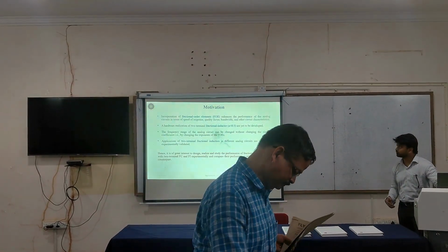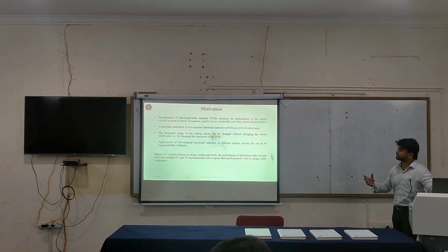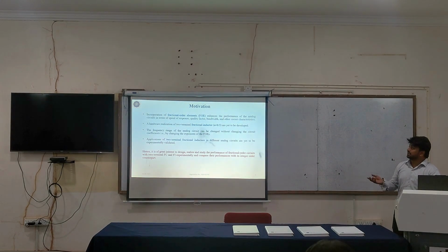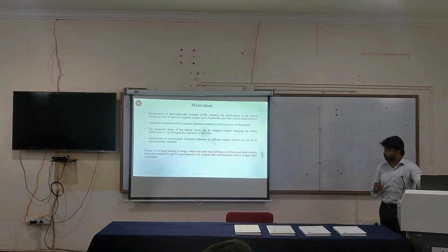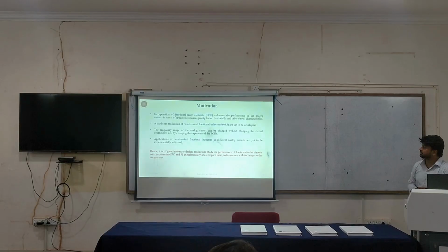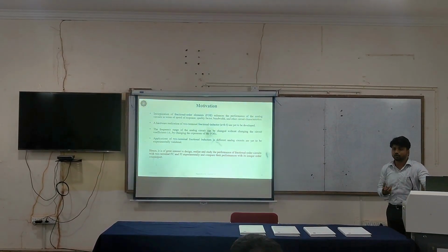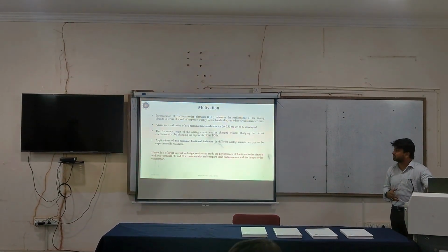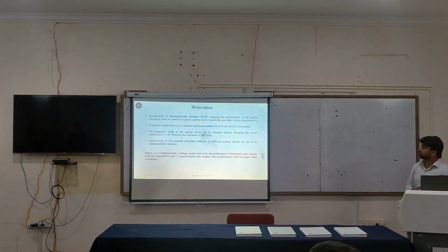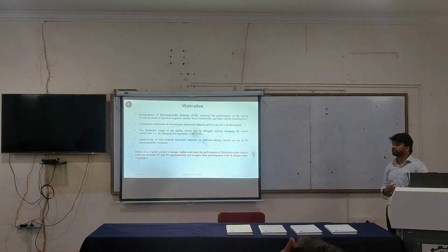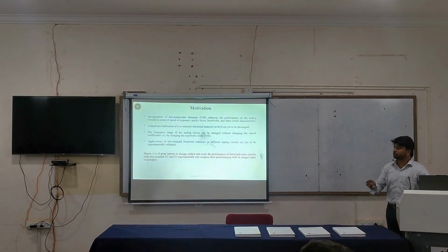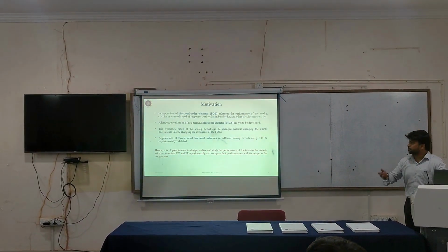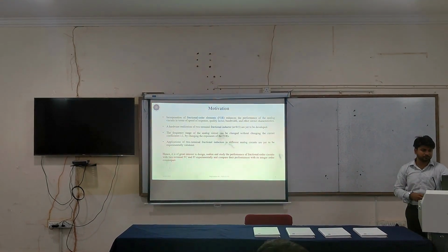Now coming on to my motivation. Incorporation of fractional order elements enhances the performance of circuits and systems. Hardware realization of a two-terminal fractional inductor of order less than 0.5 is yet to be developed. The frequency range of analog circuits can be changed without changing the circuit coefficients or the RC time constants. Application of two-terminal fractional inductors in different analog circuits is yet to be validated. Hence, it is of great interest to design, realize, and study the performance of fractional order circuits with two-terminal FC and FI, that is fractional capacitor and fractional inductor, and experimentally compare their performance with the integer order counterpart.